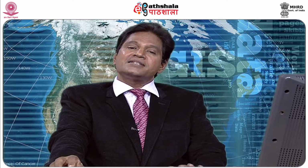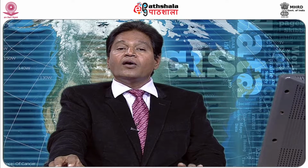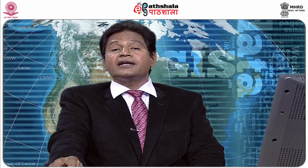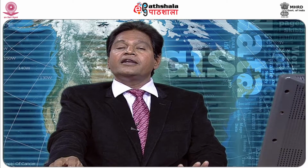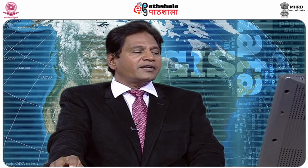Another study is impact assessment, in the sense that by bringing up a specific factory or anything else in a given area, what is going to be the impact on land, air and water, environmental impact assessment. So, normally we study with the buffer technology, we use a 10 kilometer buffer, identify the existing land use and we predict what will happen to the entire area and the surrounding over a period of time if this particular factory or a quarry is allowed. So, that is a very good application for EIA, where GIS plays an important role. It is a very simple tool, we can use it effectively.